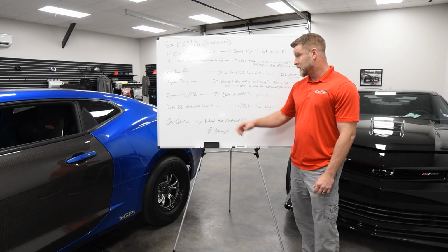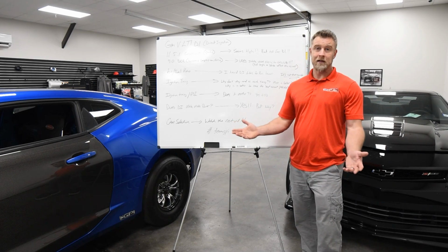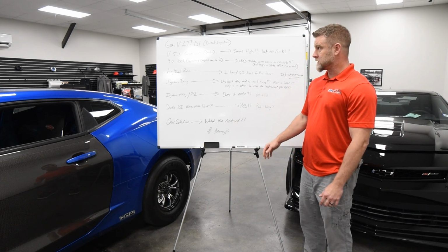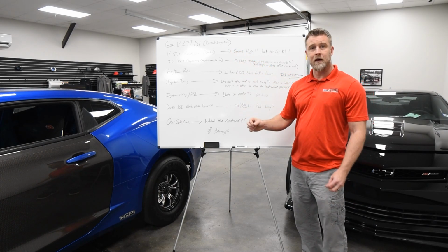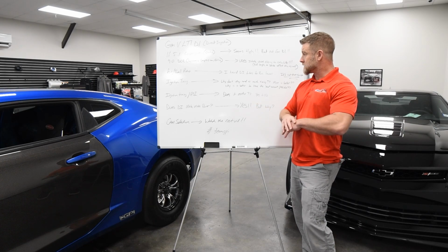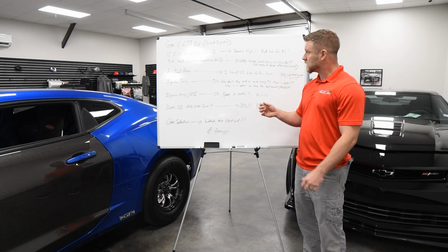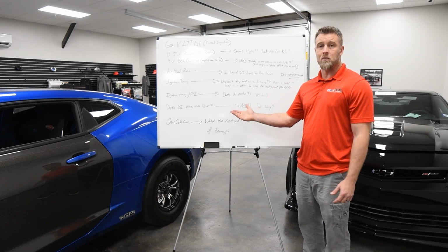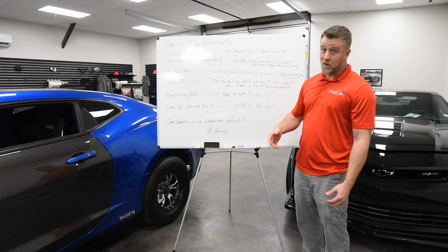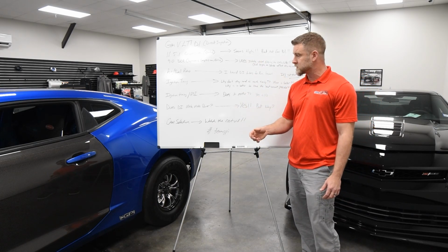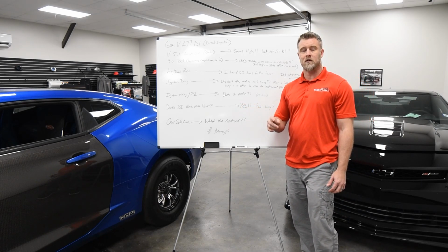And does DI make more power than port injection? Absolutely, it does, yes. As we talked about earlier in the video, the benefits of DI with the better atomization and better combustion event. It just makes more power, and the compression ratio plays into that as well. I mean, that obviously helps, but the DI is worth power over the port injection when you can run 100% direct injection.